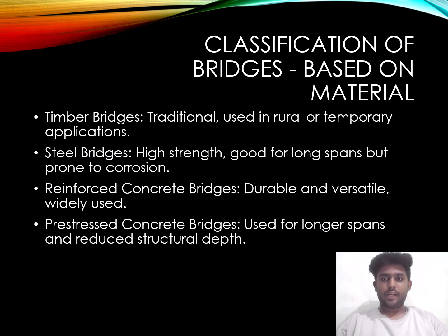Next, classification is based on material. Timber bridges, traditional, used in rural or temporary applications. Steel bridges, high strength, good for long spans but prone to corrosion. Reinforced concrete bridges, durable and versatile, widely used. Pre-stressed concrete bridges used for longer spans and reduced structural depth.